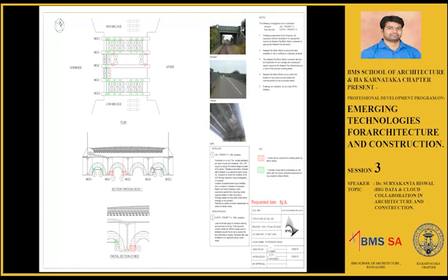The traditional damage detection technique that the asset engineers use is to dig a hole near the steel section and look at it. So physically they create holes, which means they are introducing damage. They wanted to avoid this technique. They want to go for some NDT through which they can identify damage without damaging the structure in the process.